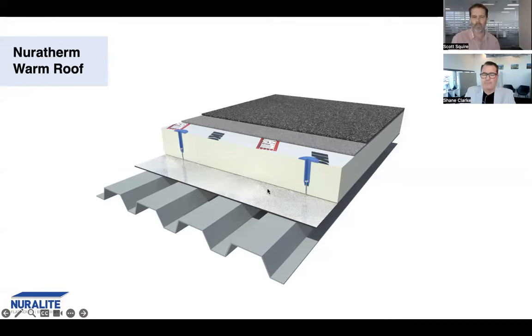And you can also see in the build-up, we've got an independent vapor barrier. Now, obviously that metal is fast to install. Once it's installed, the top of the metal gets primed and the vapor barrier goes down. Once that vapor barrier goes down, essentially the building's watertight for construction. So in terms of construction program, the efficiency on site is just so much better than that cold plywood membrane construction that we showed previously.